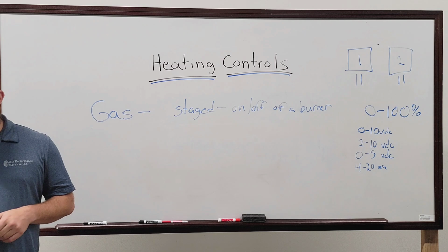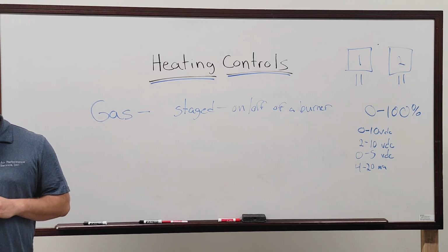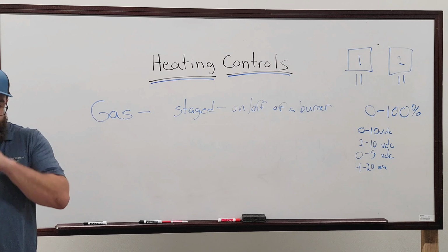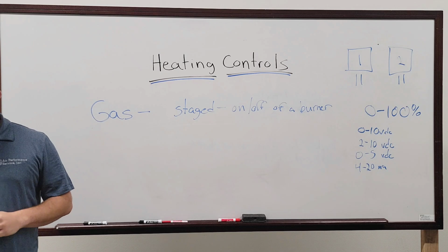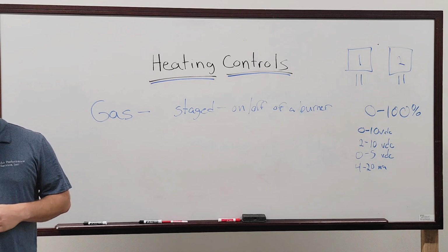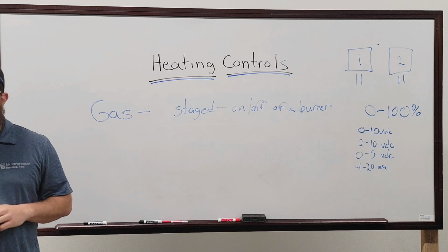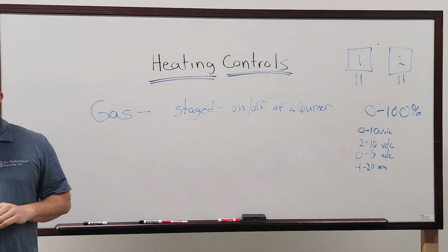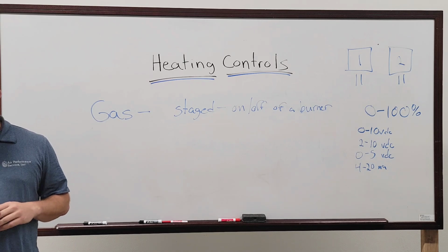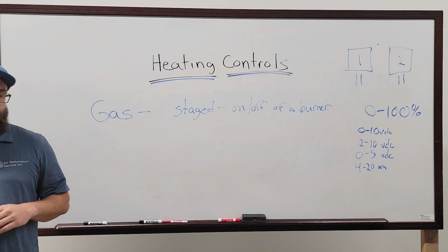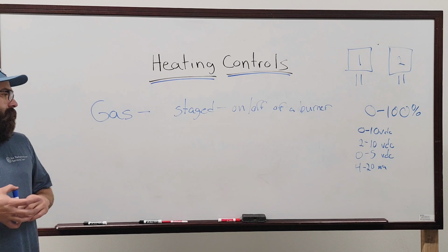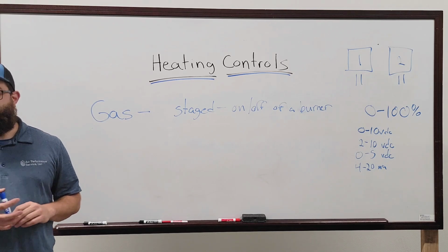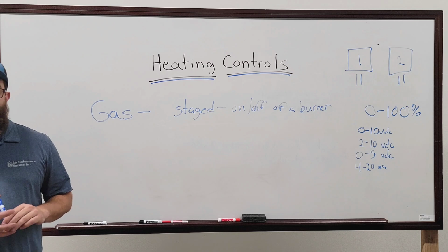Rarely did we ever control them. We do from time to time. I actually just went out and troubleshot one the other day in a pump room on a roof. Just a little small electric, I think it was 110 volt, little tiny guy, but it had a communicating wall thermostat on it. So just standard on/off, W1 G type control with a communicating interface on the thermostat though. So no programming on our side. It just gives us a readout basically.